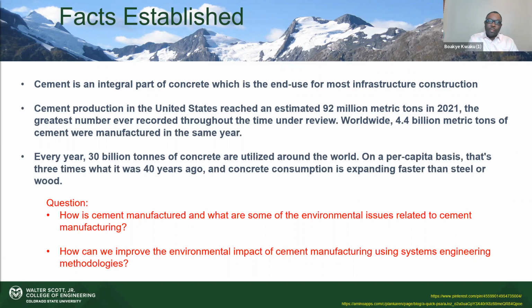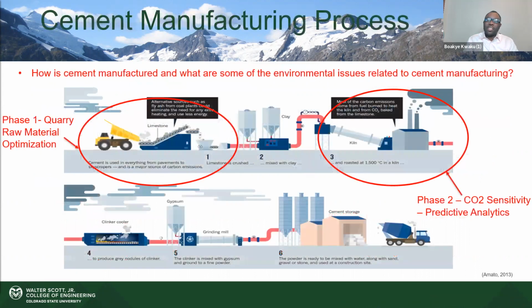How is cement manufactured? In cement manufacturing, the process goes through a series of phases. We start by first getting the raw material. Ninety percent of that raw material comes from the ground, which is limestone. The reason limestone is more suitable is because of calcium carbonate. Limestone is made out of calcium carbonate. Even with that, a percentage of calcium carbonate with less impurity is required. If you look on the screen, the first part is the limestone, which is this. We obtain limestone through quarrying.